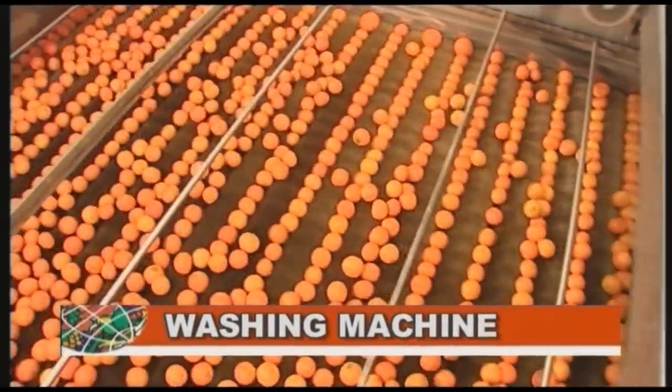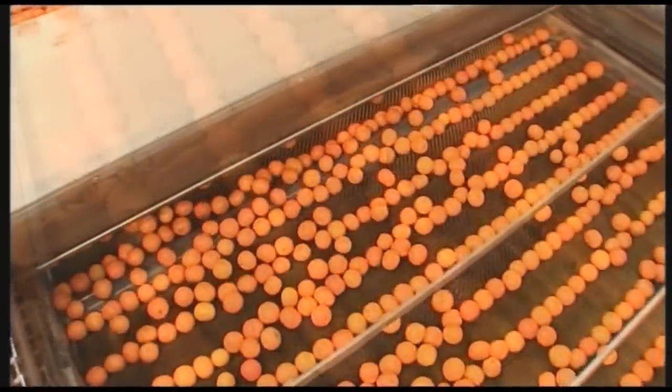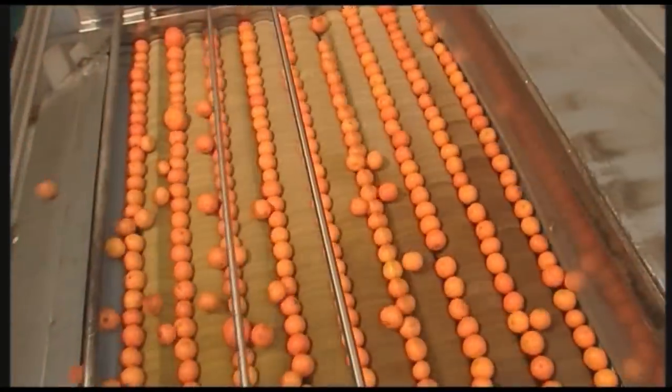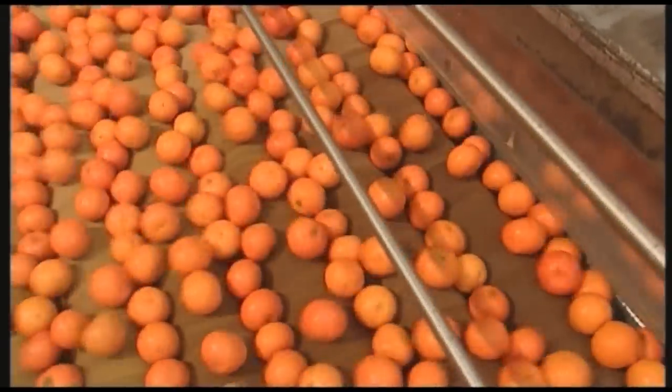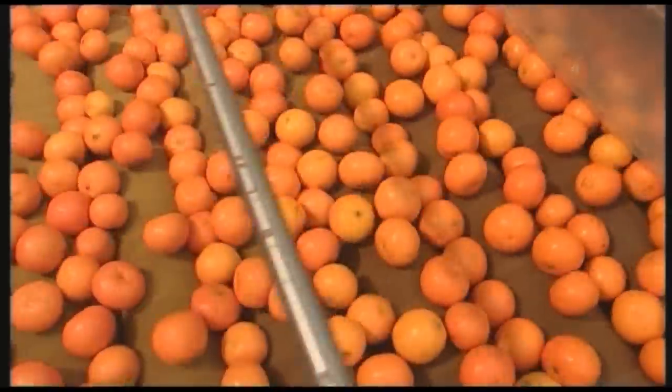The speed of the brushes on the fruit washing machine is adjustable. The programmable pneumatic strainer with variable tension eliminates the water absorbed by the latex rings as the fruit passes. The machine is also equipped with a computerized detergent and fungicide dispenser and a motorized fruit extractor to regulate the time the fruit remains in the machine.